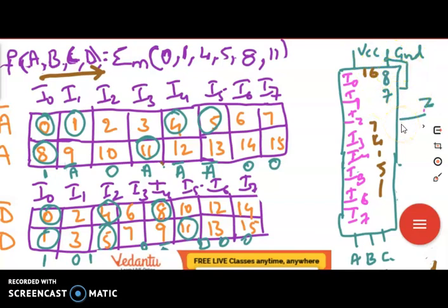So pin number 5 is our output. So we'll be extracting the output across this. So these pin numbers, you can just look into the pin diagrams and write down what is I0, I1, I2, all these pin numbers. And these are the select bits, that S2, S1, S0, that pin numbers you can write it down. So then we need to draw the circuit here.